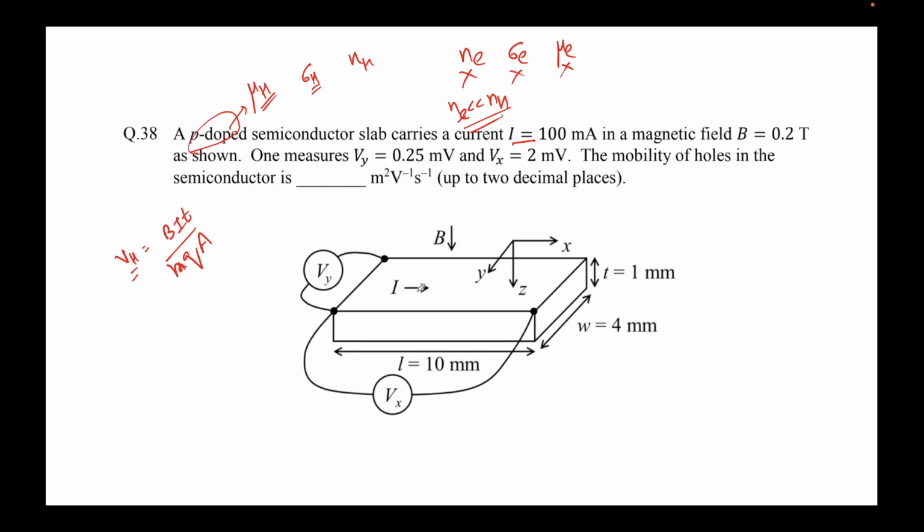So let's say electron is traveling here. Electron will be traveling in this direction. Current is flowing. Electron will go here. So again, I'll apply F equal to QV cross B. Oh, electron won't be here. It's a hole. So hole will be traveling in this direction. Hole charge is positive, so this is positive. V is positive I. This is my coordinate system, I, J, K.